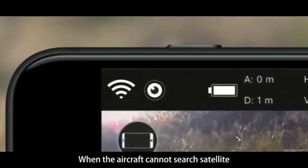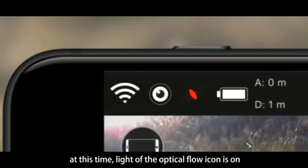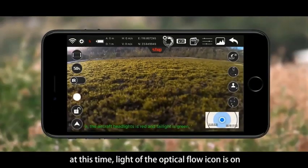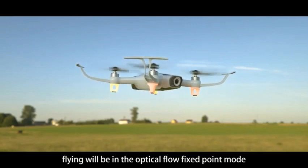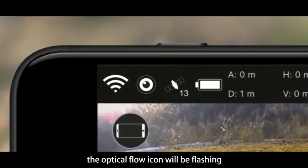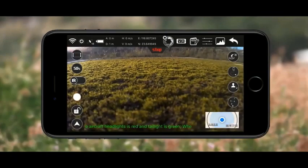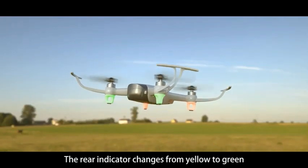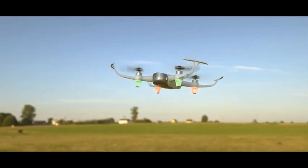When the aircraft cannot find satellite signals, the GPS icon will be flashing. At this time, the optical flow icon light is on, and flying will be in the optical flow fixed point mode. When the aircraft can find satellite signals, the optical flow icon will be flashing and the GPS icon is static. The rear indicator changes from yellow to green, and the aircraft enters GPS flight mode.